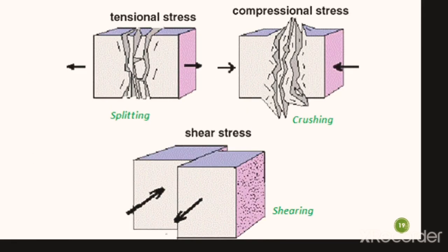Prepare that. Let me conclude today's class with this slide. Okay, so these compressive stresses, tensile stresses and shear stresses are going to lead to the failure of the member, failure of the body. How is the body going to fail? See here, if you see the tensile stresses here, these tensile stresses are trying to split the body. So the body gets split into two halves, and that is how it fails. But if you see the compressive stresses here, because of these compressive stresses, this body is going to get crushed.